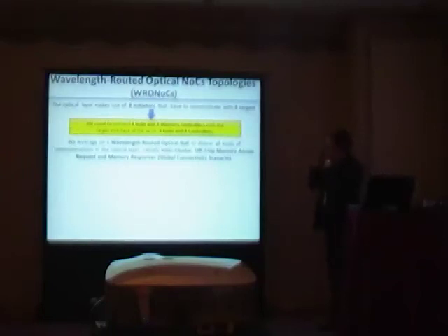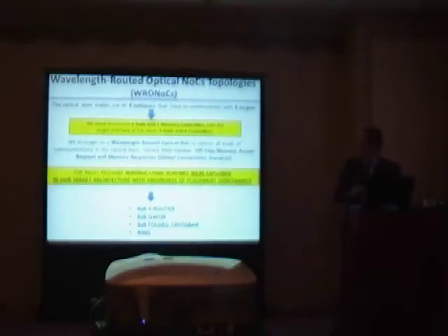In our optical layer, we have to connect 8 initiators with 8 targets. And one possible way is to leverage a wavelength-routed optical NoC to satisfy all communication requirements, inter-cluster, processor memory communication, and so on, in order to enable global connectivity. In fact, all the most relevant wavelength-routed optical NoC logic schemes proposed in the research literature, such as lambda router, Gwor, the crossbar, and the ring, were explored in our work with awareness of placement constraints, of physical constraints.